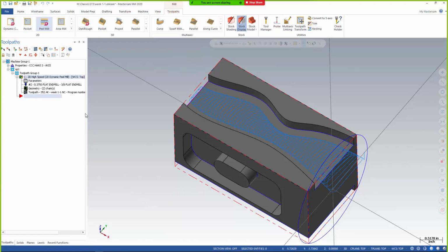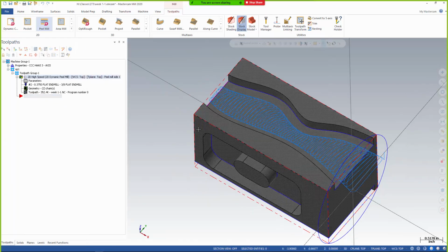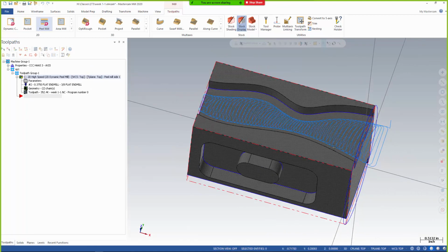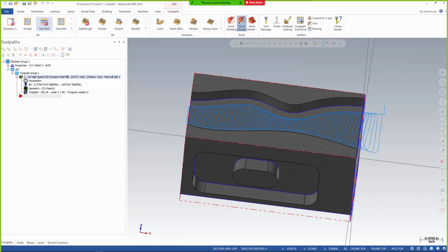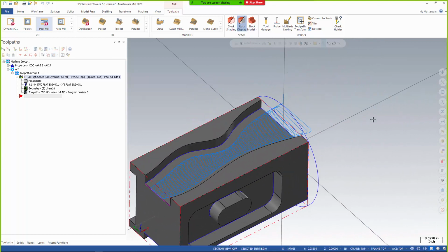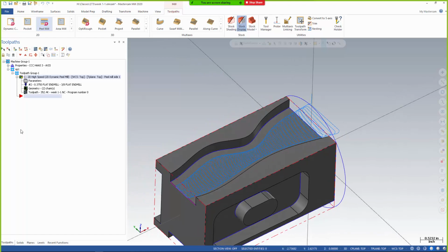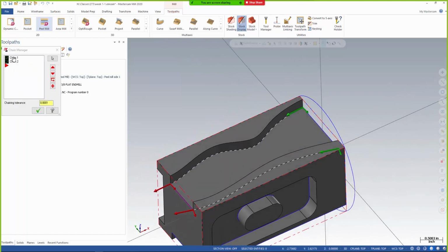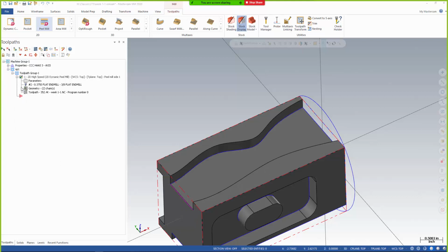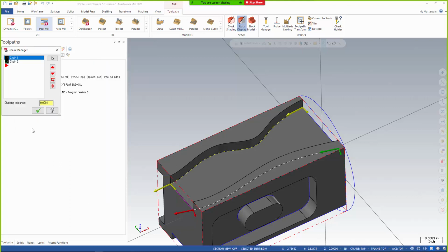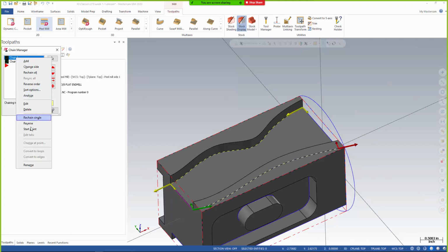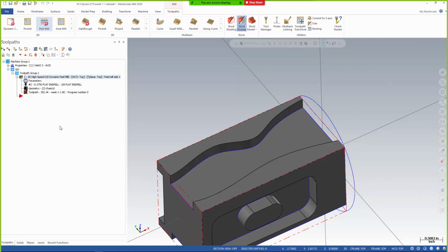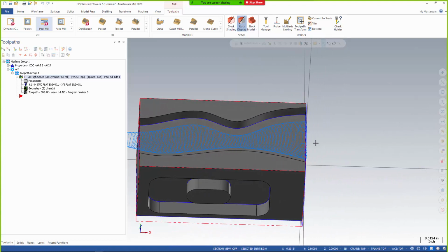And it's important that you try to note what's going on here. With this peel mill, I can use a finishing operation. I'm also probably going the wrong direction, to be perfectly honest with you, because this is my sub spindle side. I probably don't want to start over there, so I'm going to go ahead and reverse those chains. So I'm just going to come in here, right click on one, reverse that chain. Well, it should reverse it, and then reverse. There we go. And reverse. And then hit regen. Now that should get it going the proper way, so I'm not spilling over too far.